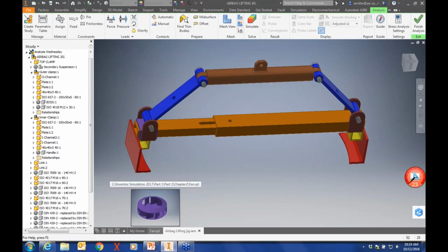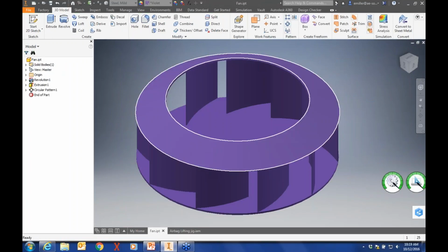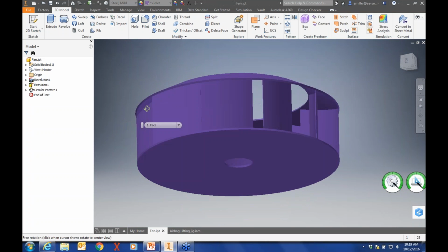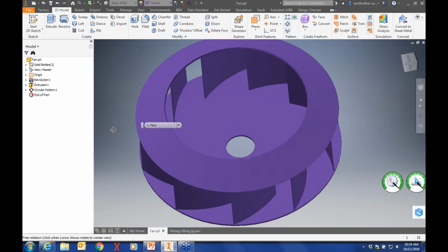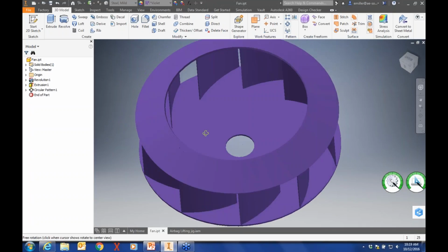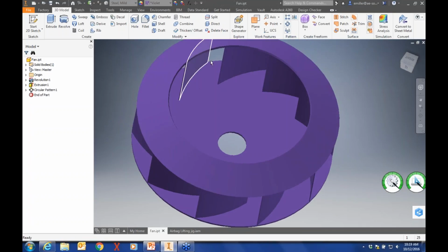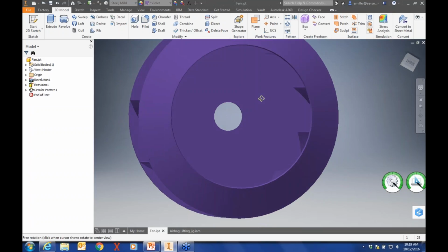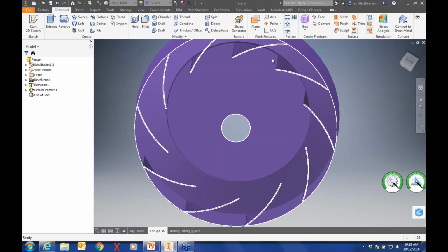I do want to look at one other thing. When we're talking about simplifying a model, here we've got some symmetry, obviously in a circular fashion. So this is just a regular fan, kind of an impeller that we want to do analysis on. So how would we simplify this? Well, first you got to kind of figure out how many there are and divide that by the overall angle, or what each piece would be.